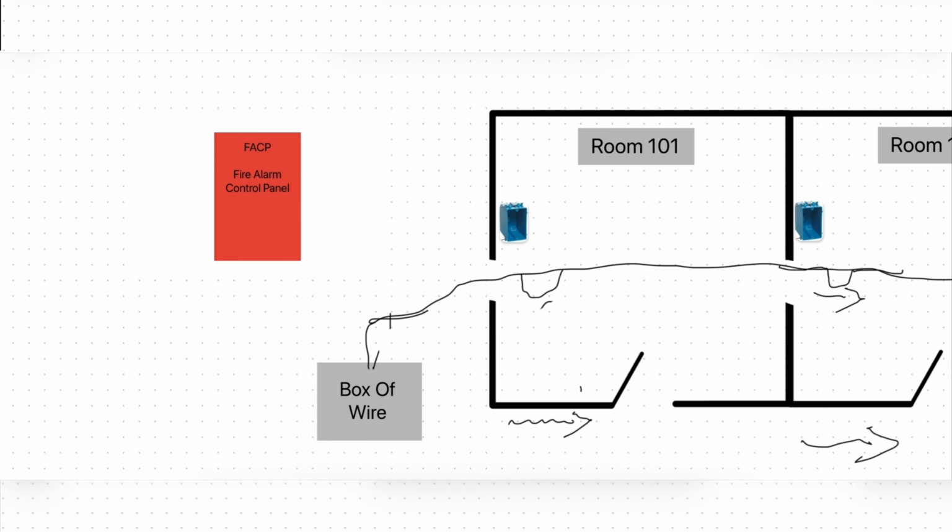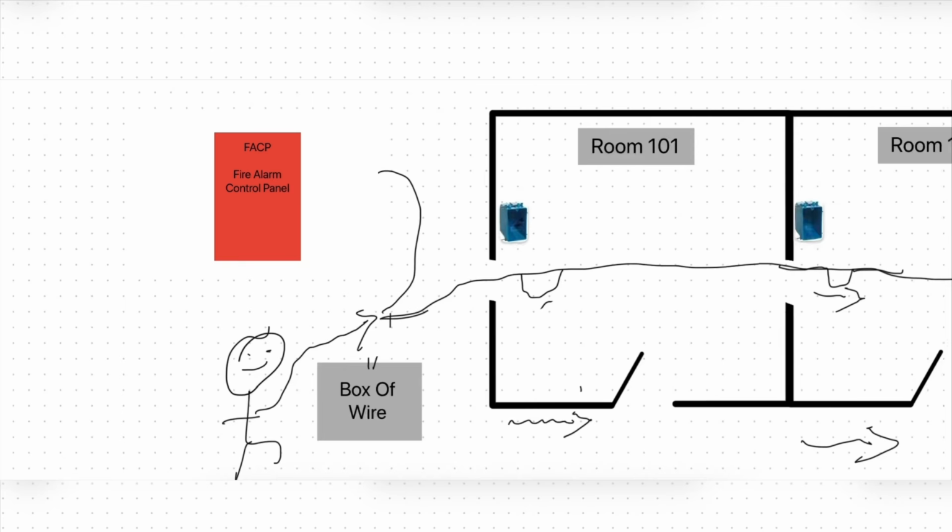Until he reaches the pull starting point in which the cable is cut and then run to either continue the circuit or to be routed into the panel. Pulling loops is a method of pulling cable. It's not a requirement. It's dependent on the volume of devices, what the scope of the project is, and ease of pulling. All said and done, these loops get cut and replaced with the NAC devices, which we'll see later.